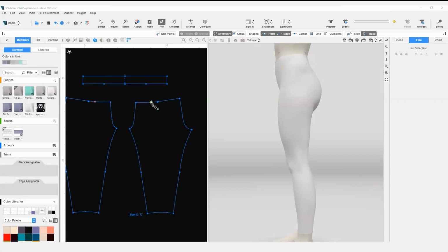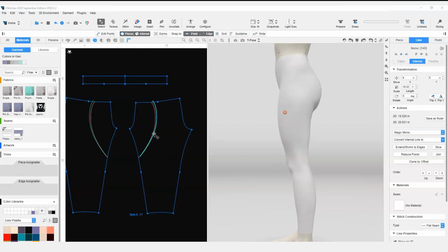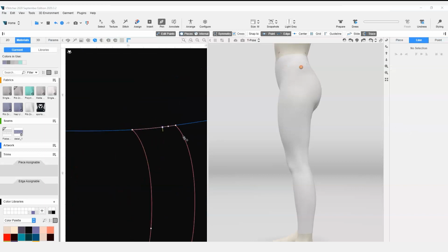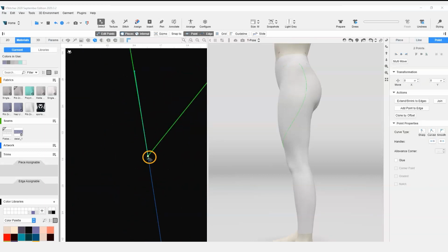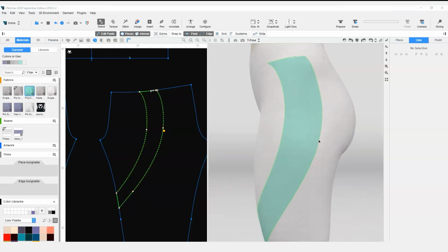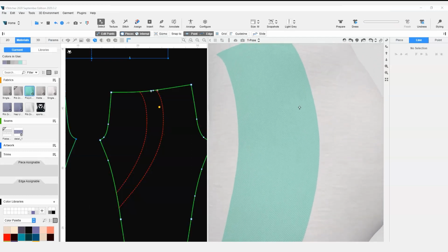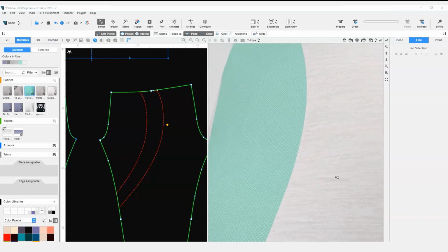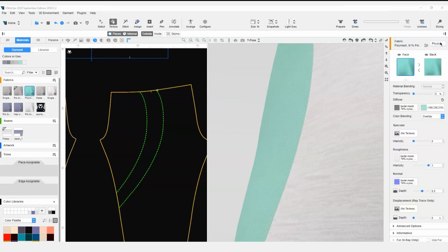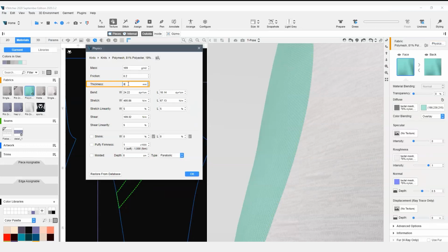When creating a closed cut mark, we can also join lines. For example, we create this line and make a copy of it and trace the outlines. We then choose both points, go to the context view and click Join. These two parts appear to be on equal planes. That's because both fabrics have the physical property thickness set to 0. Using this option creates a smooth look that fits the seamless design. If we want one of the pieces to pop out a little, we can change the thickness value to create the style effect we want.